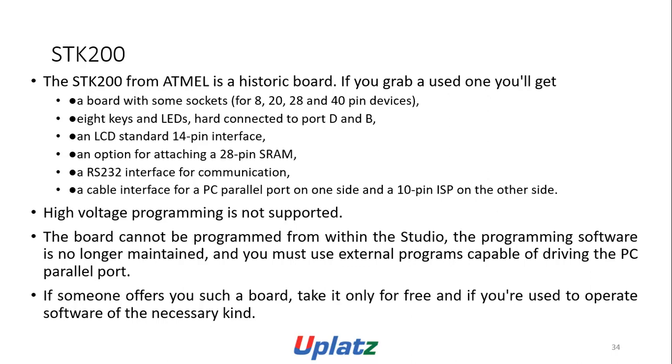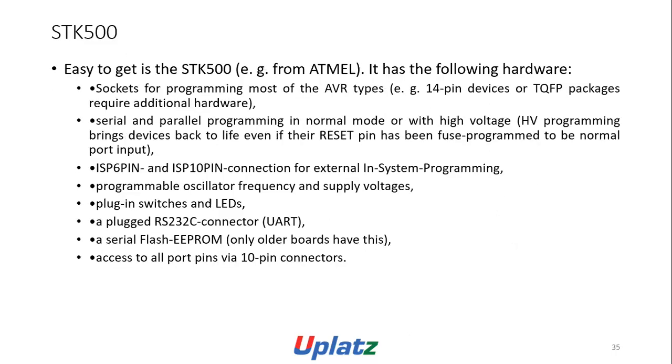It has an RS-232 interface, a cable interface for a PC parallel port on one side, and a 10-pin ISP on the other side. High voltage programming is not supported. The board cannot be programmed from within the studio. The programming software is no longer maintained, and you must choose an external program capable of driving the PC parallel port. If someone offers you such a board, take it only for free, and only if you are used to operating software of the necessary kind.